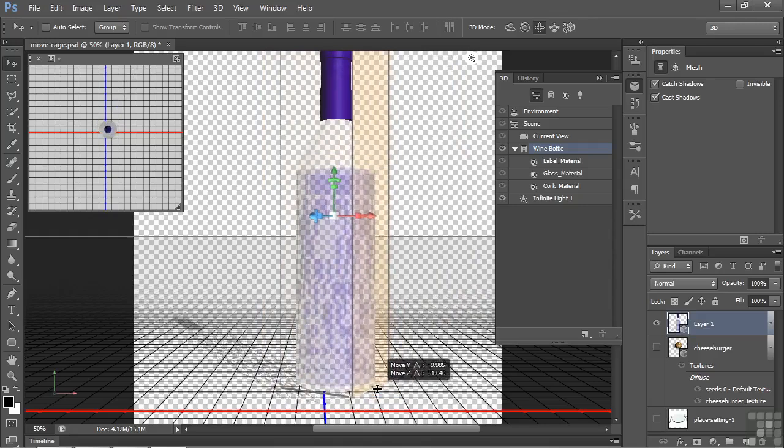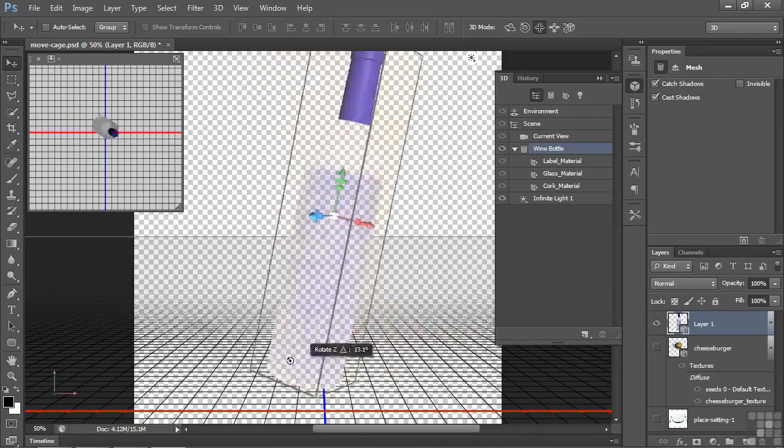If I want to rotate it along, let's say, the X-axis, X is this red thing, Z is the blue thing, red, green, and blue, RGB, X, Y, Z, that's how you can remember the colors. We're going to deal with the widget in the next lesson. Let me go down here a little bit. If I hover right there, the rotate around the Z-axis, that's the blue one. Now, it's not going to rotate along the bottom as you might think. It's going to rotate around this widget. So I go down here, rotates on the Z-axis.